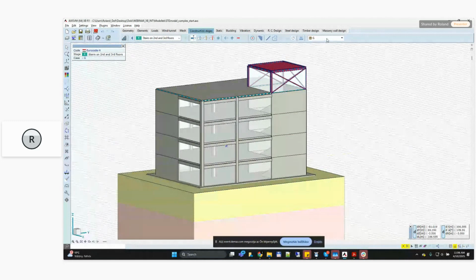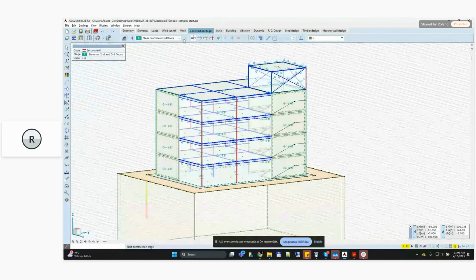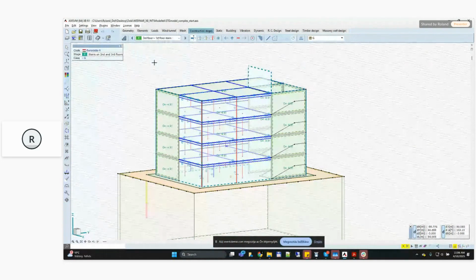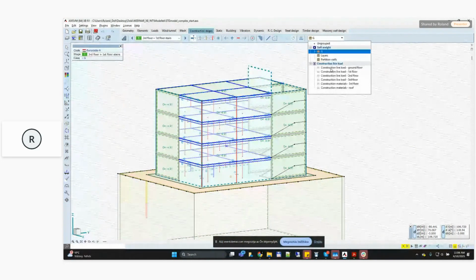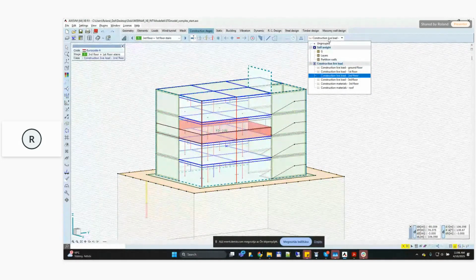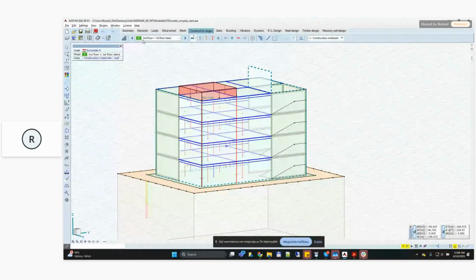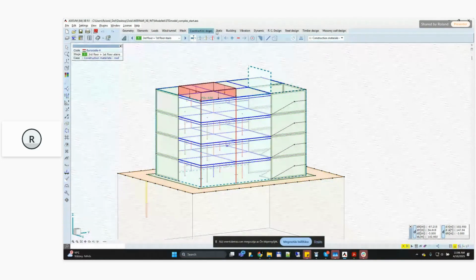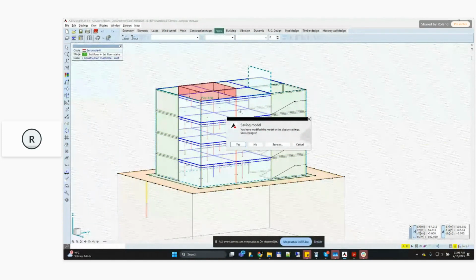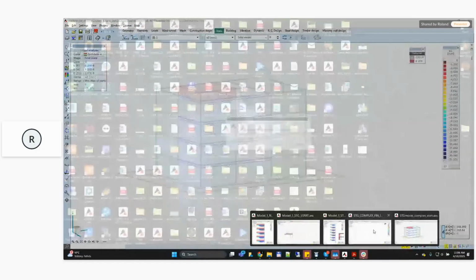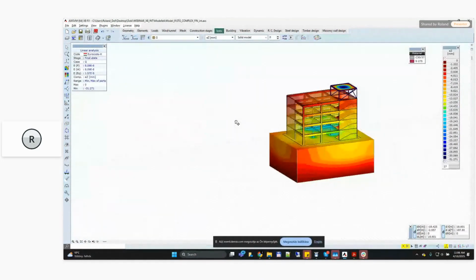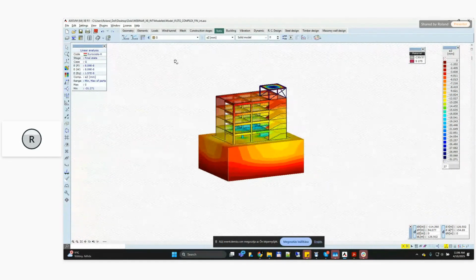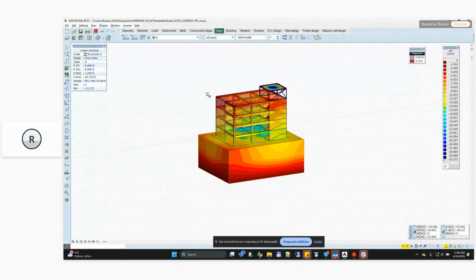And after I click on the OK button, I can track in a specific case what kind of loadings are there. All of them are listed in this drop-down menu, and I go through from stage to stage. Okay, everything is ready, and I can continue with the static calculation. This model would take around 5 minutes to calculate, so to spare some time, let me change to an already calculated model and check some of the results and how you can navigate through the results.